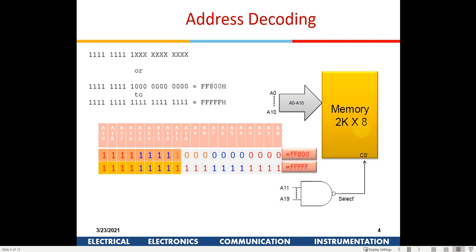For any specific purpose, say we just have to use 8086 to read something, for automating, say, a washing machine, you don't require so much big memory. So we are going to use the smallest available memory. We'll select a small memory chip and accordingly modify this hardware. Is it okay? Yes, sir.